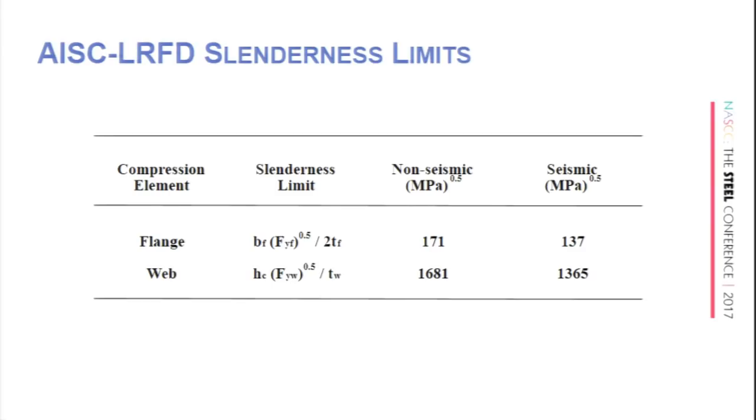And there are several reasons to make sure that you know that there's 2 things that affect your slenderness. It's E and it's Fy. Again, my materials are not all carbon steels, and my yields are not all A992. So I get both ends.